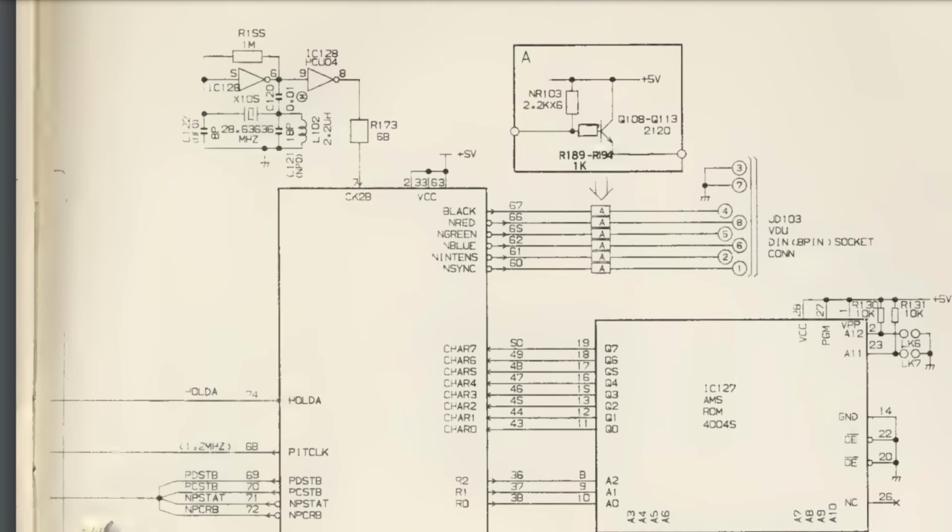So at any rate, it looks like we're going to have to do something a little bit tricky here to make this work. So the thing that springs to mind is to use the programmable interval timer. We know that that can be 100% synced with the video chip since it runs on the same crystal here.